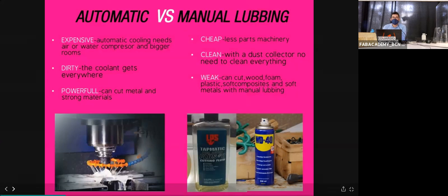In open setups, we can do what is called the manual lubing. For example, cutting aluminum, even with the proper setting, sometimes you're cutting for long times, the aluminum gets quite hot. You want to avoid that the metal gets quite hot, and you want to soften as much as possible. So what you can do is, meanwhile the machine is cutting, spray a little bit of lubricant or cutting oil on your material to help on the cut. Not mainly to cool down, but this is widely done to extend the tool life length. It means the total amount of cuts that your tool can produce. So if you don't use cutting oil, your end mill can last only like 2 hours of cut. If you use cutting oil, for example, you can extend it to 3-4 hours, just to extend the tool life length.